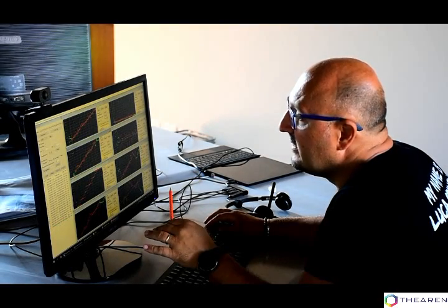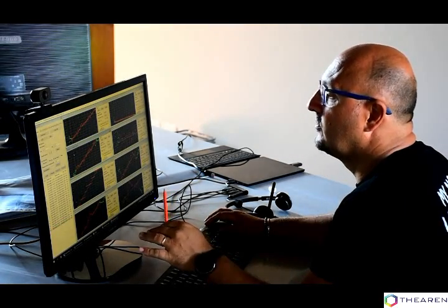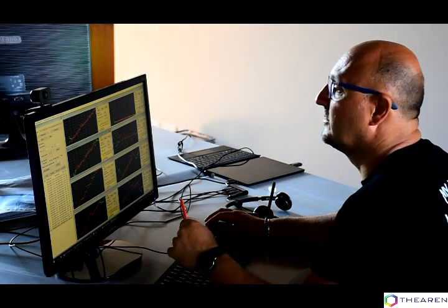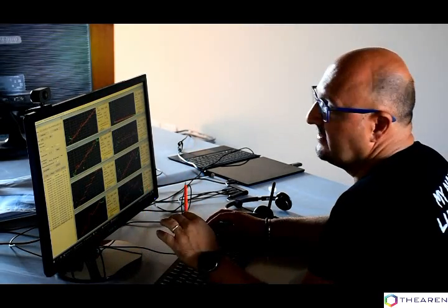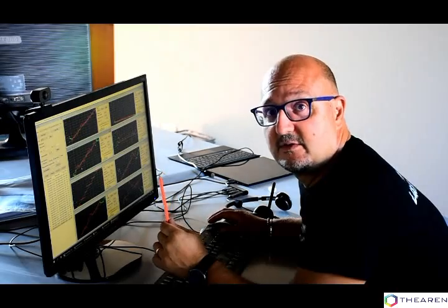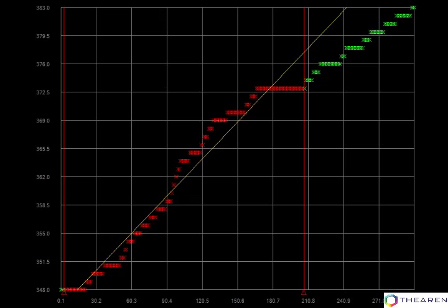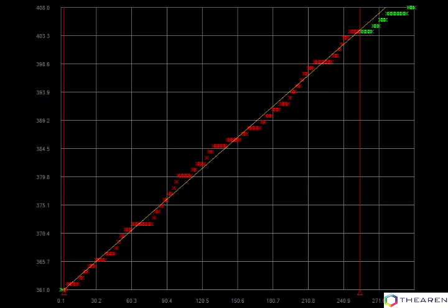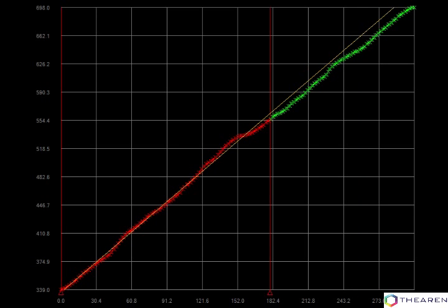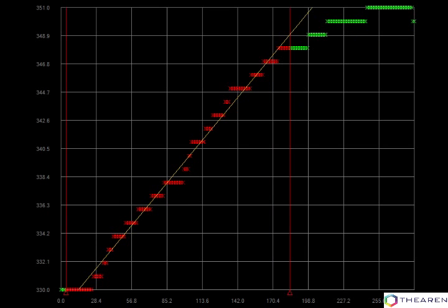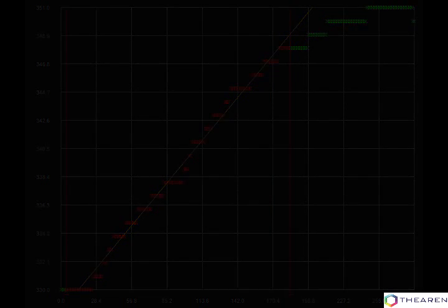Data processing for each campaign, for each gas, considers air or physical parameters for the calculation of the emission flow rate, interpolation of the valid data and statistical regression of the values, quantification of single points of emissivity, statistically robust calculation of the emission value of each measured point, and the relative confidence limits for each measured parameter.